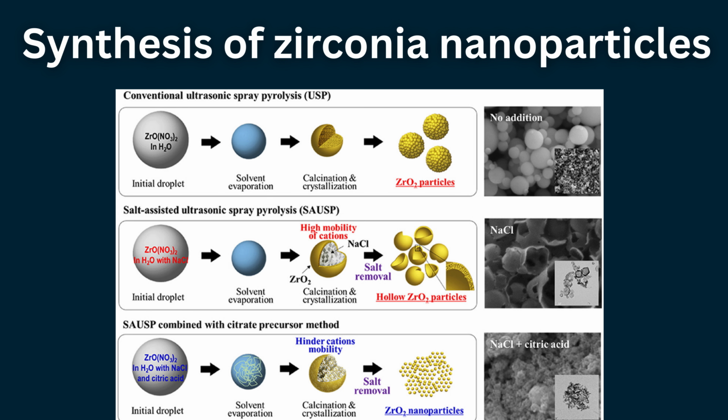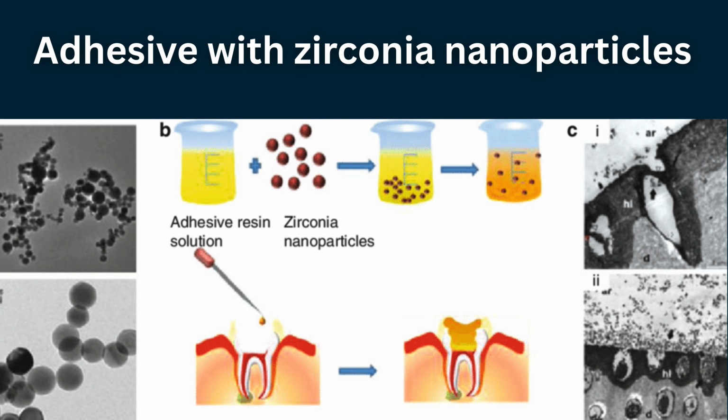Zirconia nanoparticles. Zirconium dioxide, zirconium oxide, is a ceramic widely used in dental applications because of its high strength, fracture toughness, fatigue resistance, and biocompatibility. When incorporated as spherical nanoparticles in dental adhesives, zirconia acts as a reinforcing filler and increases tensile strength. The presence of zirconia also enhances bonding to dentin. However, its high hardness may contribute to wear of opposing teeth. Hybrid fillers such as zirconia-silica nanofibers have been developed to improve performance.